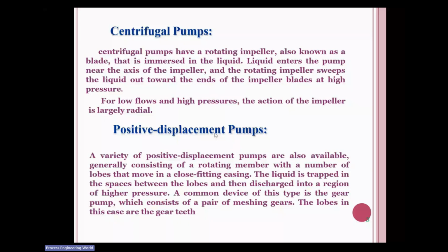If your positive displacement pump casing is not designed for that higher pressure, and if your pipeline is designed for higher pressure, your casing will burst. If your casing is designed for higher pressure but your pipeline is not, your pipeline can burst. One of my friends says here that we install a PSV. A PSV is a pressure safety valve, which is used for the protection of any of our equipment, whether it is a vessel or a pipeline. So PSVs protect our equipment from overpressure.